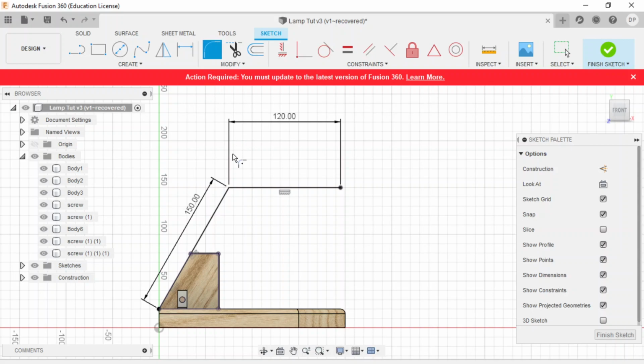Let's say I'm going to use the fillet tool, press these two lines, and I can change the diameter of this circle. I can either do it like that, or do it manually by typing in 100. So that means make a fillet, so where I have two straight lines that are joining, join them instead by a circle of diameter 100 millimeters. All right, so press enter.